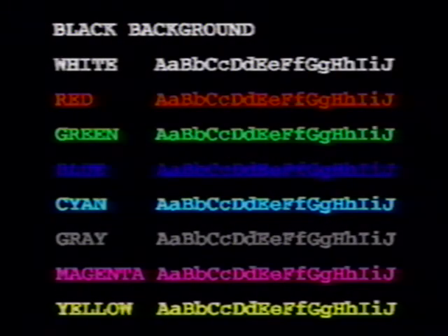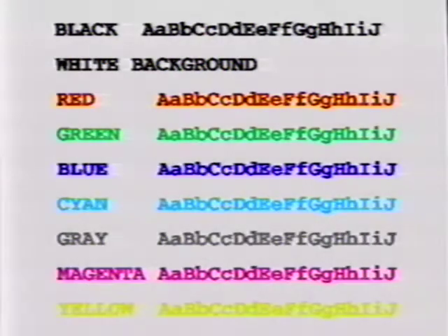Because of the way colors are encoded in a video signal, combined with the human eye's sensitivity to different colors, some colors appear sharper than others. The video signal was designed to carry more yellow-green color information than red and blue. Grayscale imagery, however, has the highest resolution and is therefore the sharpest. This means that yellows, greens, and grays appear more crisp on videotape, and reds and blues tend to bleed into the surrounding regions of an image.